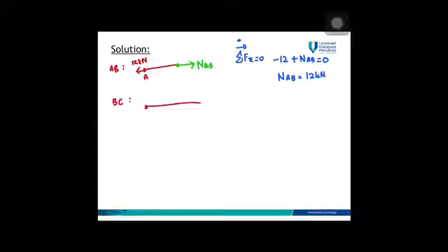This is point A, 12 kN applied load. Point B here you have 9, 9. Then please don't change the diagram. And then when you section, when you cut, you expose the internal forces. I name it as NBC. How to calculate NBC? Same, by using the equilibrium equation. Summation Fx is equal to 0.